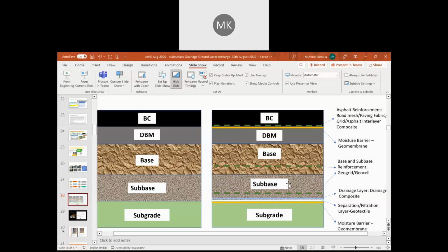Okay. So I am sure that you must have thought or written something. As a pavement engineer or a highway engineer, we all know that if drainage is not proper, it can lead to undesired water, which will cause damage in pavements. The poor water pressure built up in subgrade may lead to permanent pavement failure. Loss of subgrade support: the subgrade will become ineffective. Even if we improve it, whatever we do, if the drainage is not controlled, the subgrade will become ineffective.